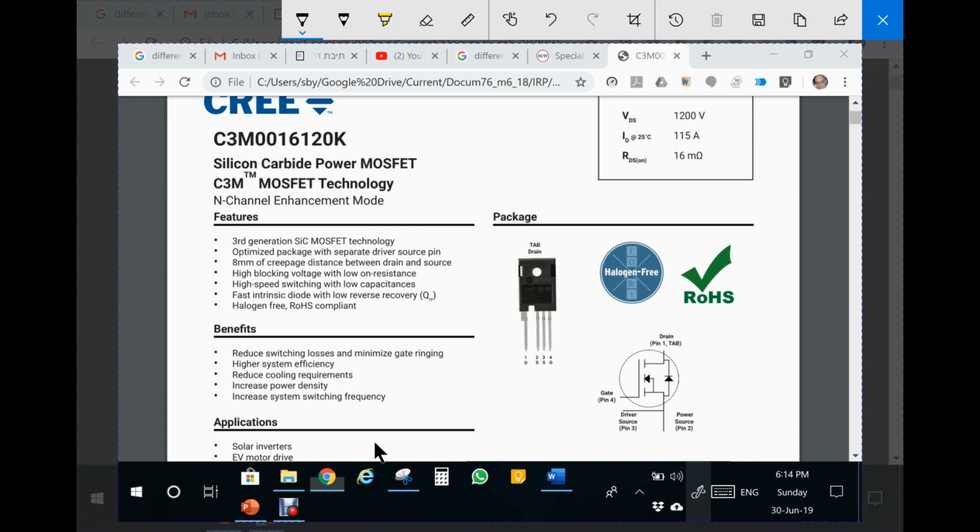So how does this relate to our case? So let's see, if you have a transistor, it will have some inductance between the source and the actual terminals and also the wiring. And this is the source. And here we have a driver that feeds the gate.